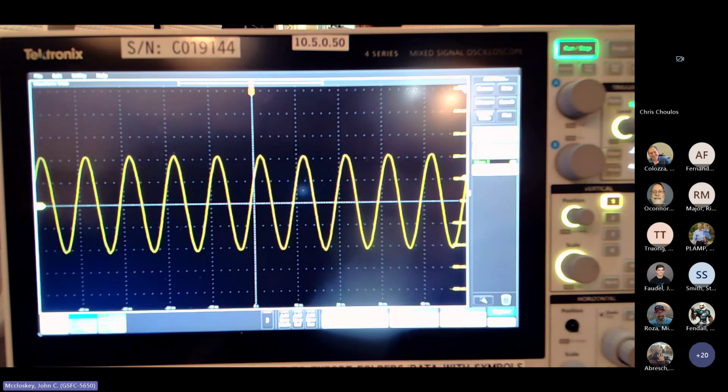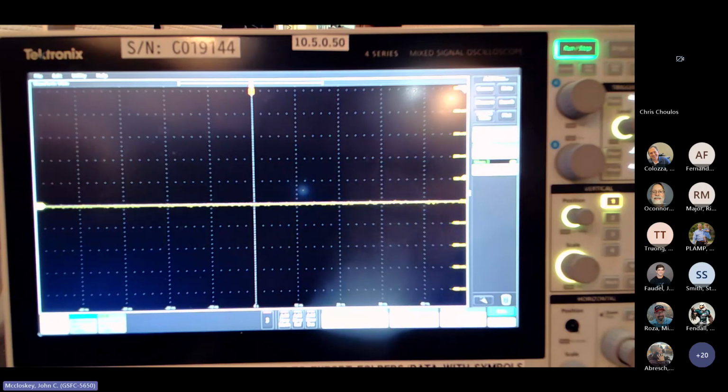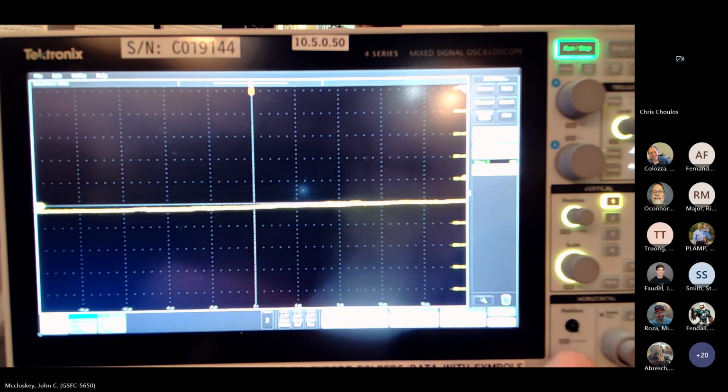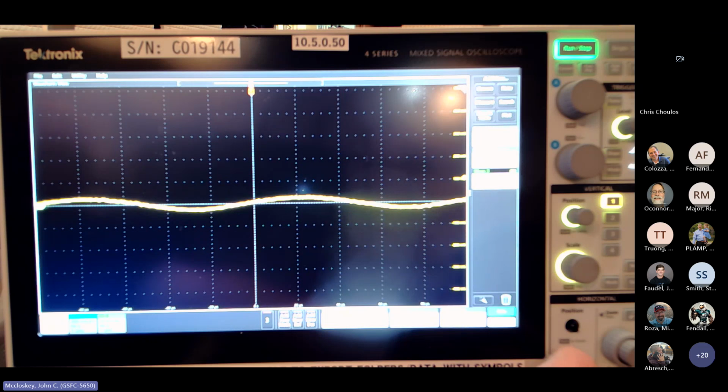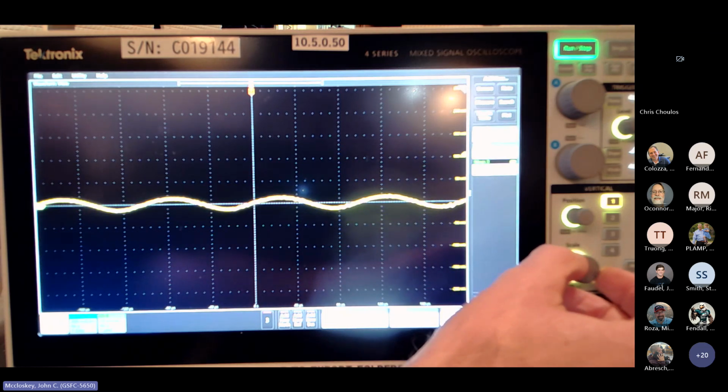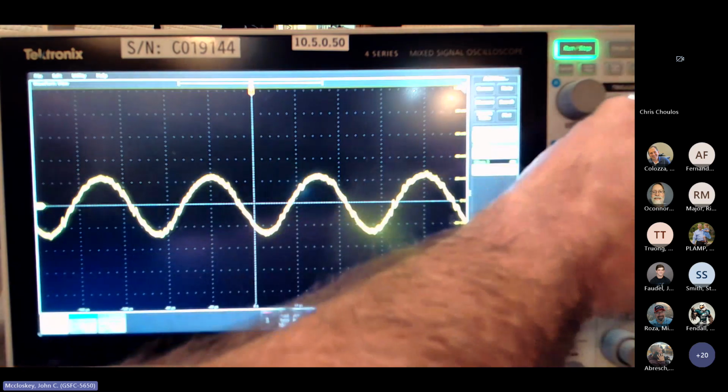So now we're going to go back to 10 kilohertz and do a simplified frequency sweep. The injection probe has a lot more loss at these lower frequencies, so you would expect it to have a lower signal level, as it does. Just a trigger.